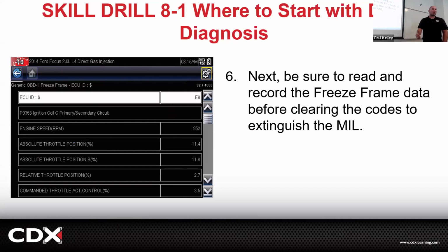You understand? So if you thought you were going to help me out when you say, hey, I got a check engine light, and I'd be like, okay, cool, what was the code? Well, it was something about a throttle position sensor, but I cleared it. I'll be like, you went on the crime scene and you just literally brought in your mop bucket and mopped it up. And now you want me to tell you what happened? Don't clear it unless you have it really well recorded.